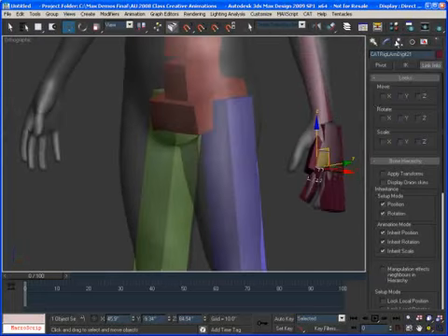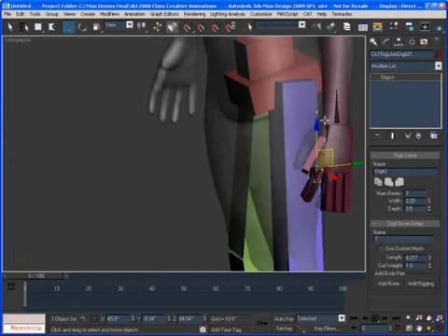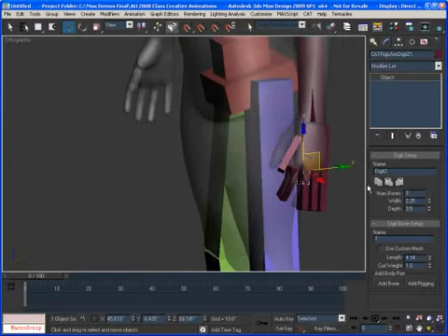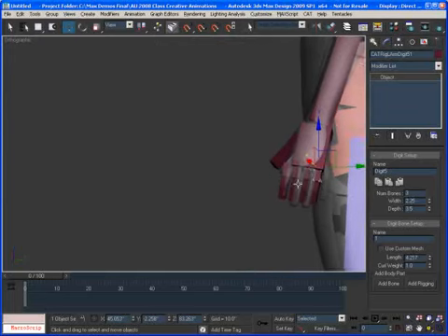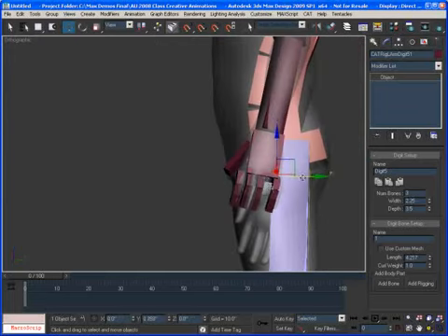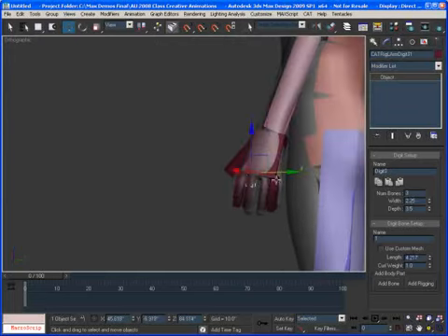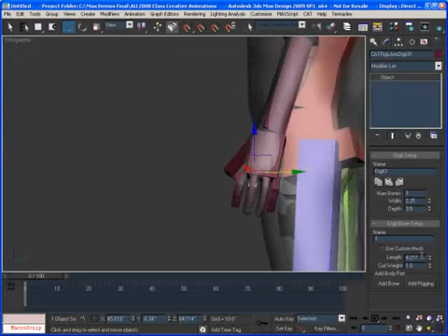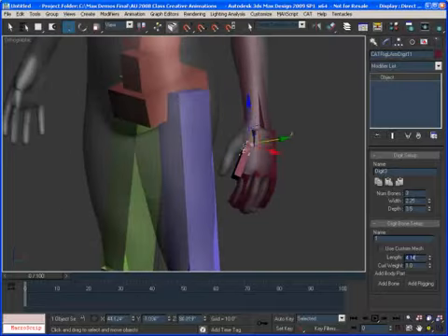And if I like this, I can go back and grab the group node for this, copy this, and paste it to that one, paste this curl on the same side, paste this one on the same side, and then I can start readjusting a bit more to fit the finger. And of course, you know, the fingers can take a bit of time, so you want to do it correctly. Like that. Anyway, so that's pretty much the idea.